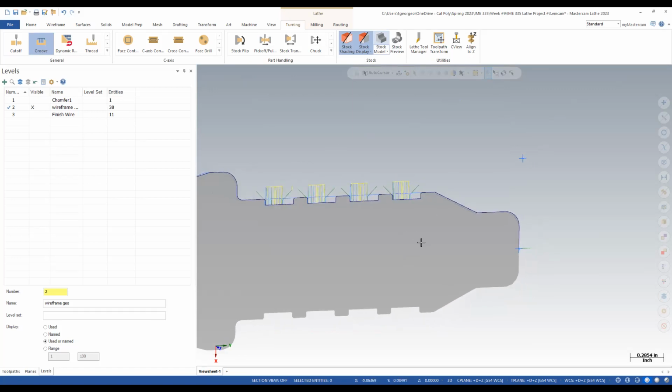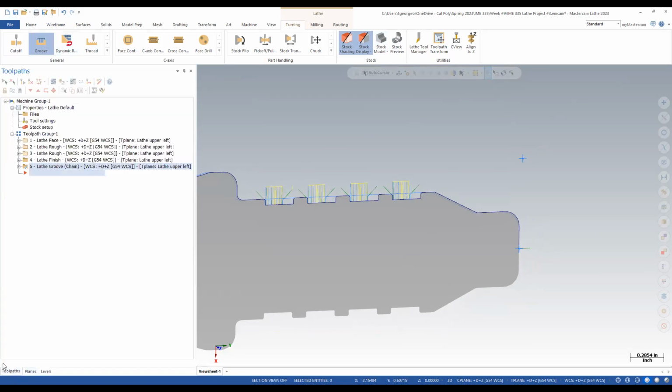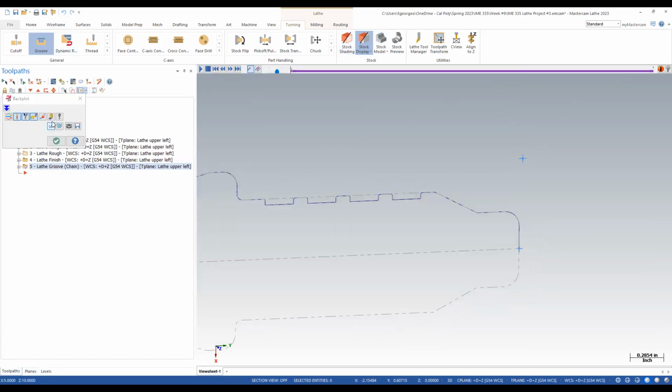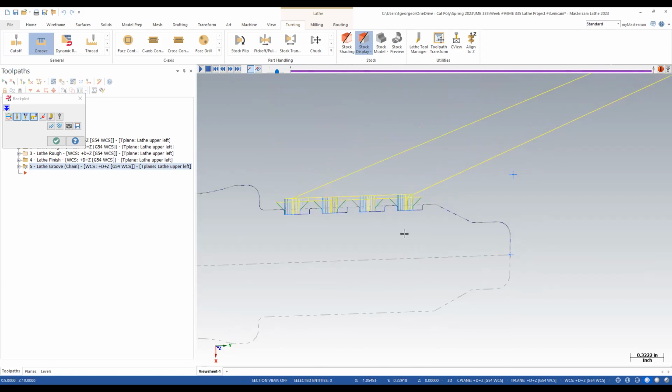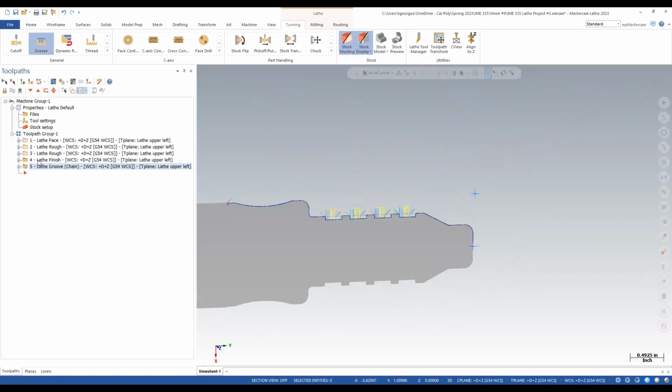Anybody have any questions on that? No, so check this out. The way the toolpath looks, I still got 15 minutes. We're good. The toolpath comes in. Maybe go a little faster. Starts grooving, and then it... Why is there such a big gap on the one side? It's the insert's thickness, right? If you touch it off on the left to the part. Cool. So it roughs them all, and then it finishes them all right there. You can kind of see that. Good to go. So check mark that.